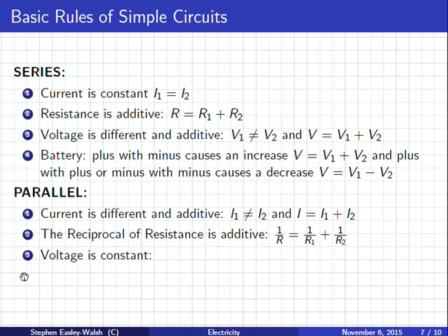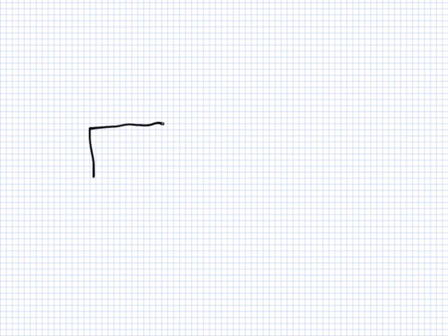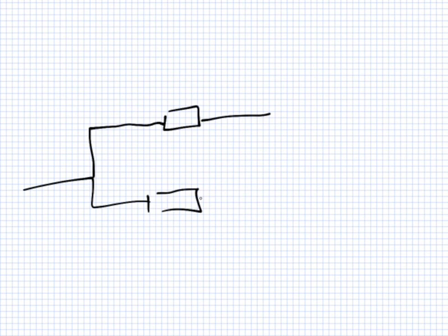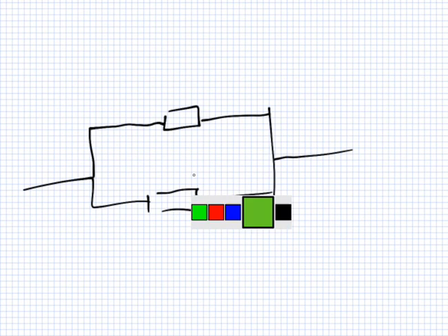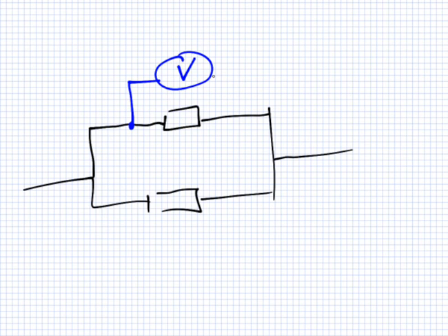So you're talking both of them in series. Everything's in series so far. Is that okay, KJ? Makes sense? You understand what I'm saying here? Yeah? Okay, so voltage is different and additive. So V1 doesn't equal V2, and total V is V1 plus V2. Yeah? Okay, next.